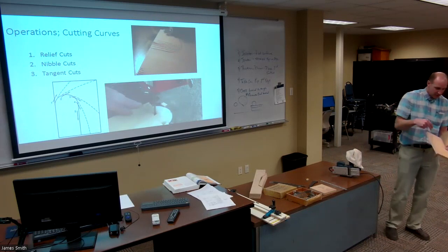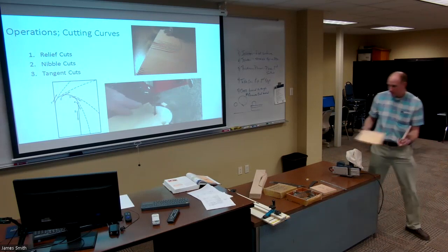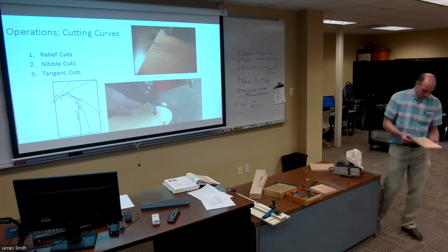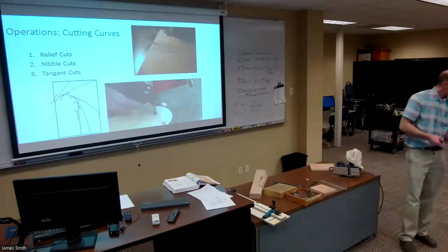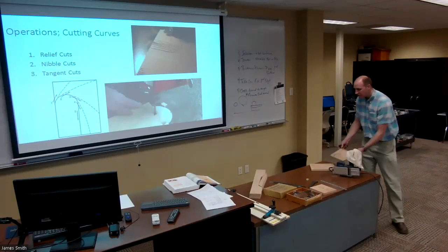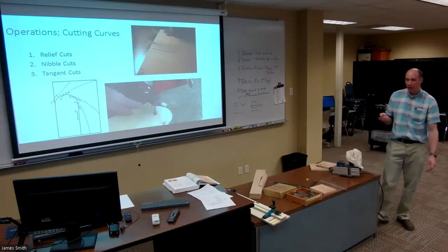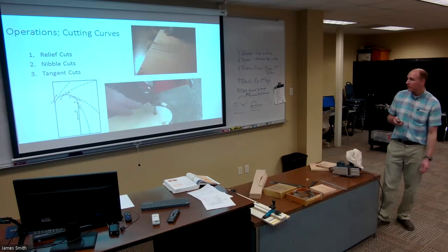Obviously, those curves are so big it won't necessarily justify the need for that. The other option is to cut beyond, back up, and then continue; those are called canopy cuts, and that's another way to create enough space to cut that radius without twisting your blade. You can also do nibble cuts like what this guy is doing.